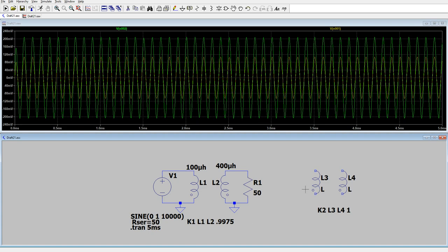When you add the transformers, you get these phasing dots, as soon as you create the coupling coefficient, these phasing dots appear. You can flip these inductors or pictures any way you want. If I grab this and, oops, need to grab it. Grab, and then rotate. You now have the dot on the top, like that. However you want to do it. So that's a basic transformer.